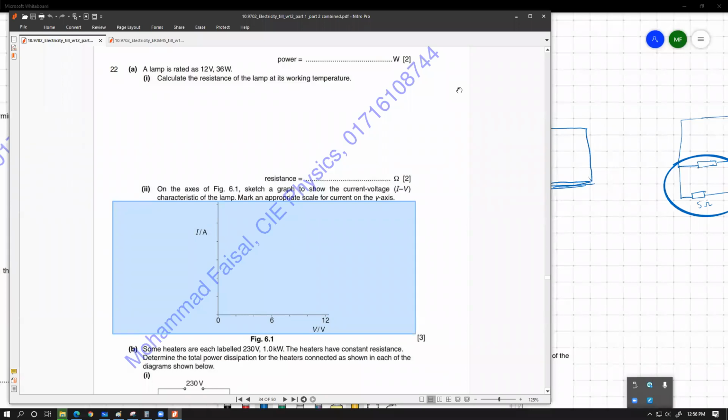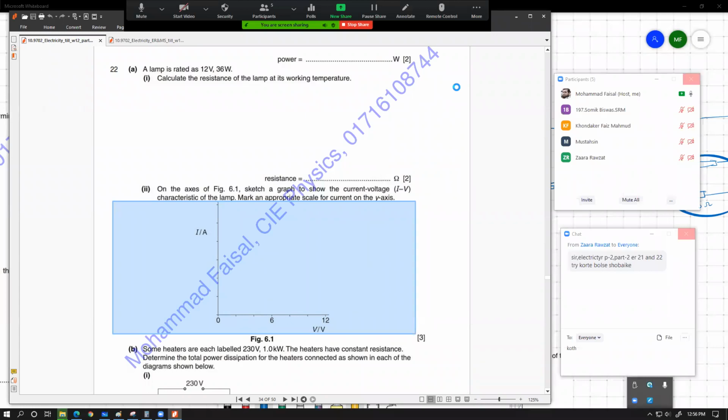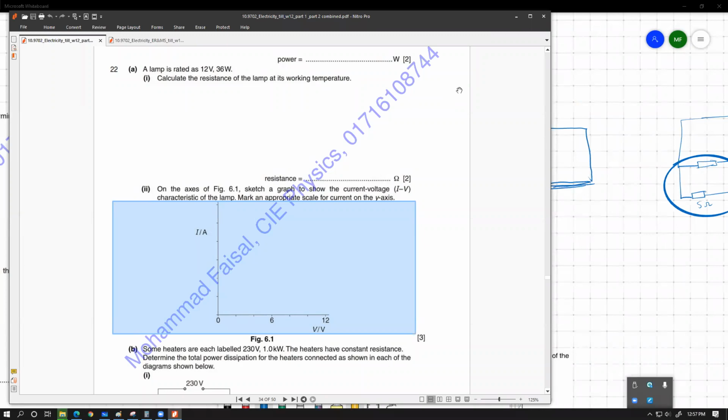The moment we start flowing current through the filament lamp and it starts to glow, from that instance of allowing the current, the filament is going to start to heat up, and that's how it will start to glow. So the temperature will increase. As the temperature increases, you will definitely have a subsequent increase of resistance, not proportional, but it will increase. So if resistance increases, you cannot have a straight line graph. A filament lamp, metal filament, is not an ohmic conductor. With temperature, its resistance gets significantly affected. ঠিক না? ইয়েস স্যার।